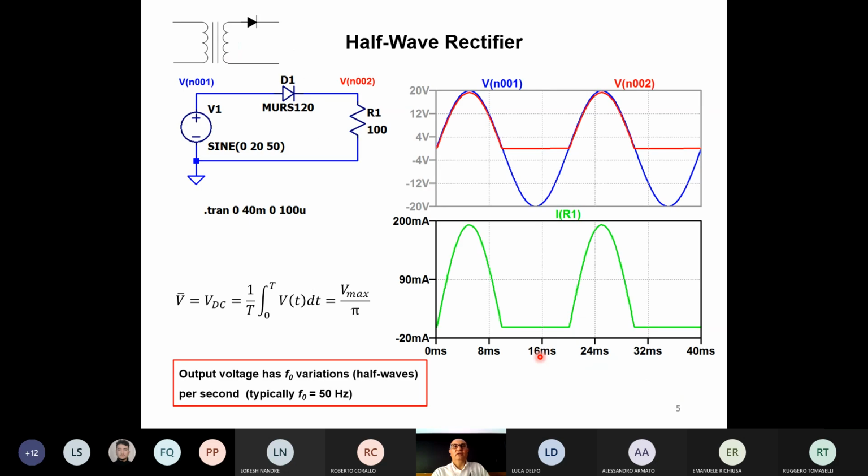So now we can see the different circuit. And for doing this, I used the software LTspice. I've done a simulation of our circuits. So the top circuit is what we are considering. Just for simulation reasons, I have removed the transformer, and instead of the transformer, I've placed an equivalent generator, which gives the voltage coming out from the secondary of the transformer, okay?